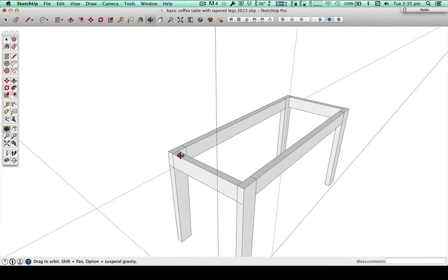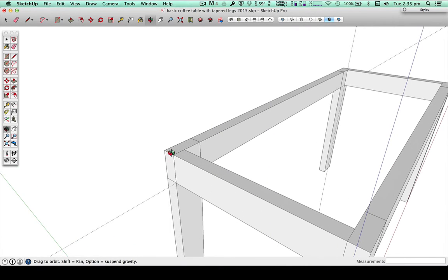So what I'll do is just start drawing the tabletop off to the left. I'll show you a trick while we're there, might as well. I showed you before how you can put a guide on a line. We can just grab a line down there anywhere, stop it here. And I might start drawing my tabletop along this guide. The other thing I can do is just click here and drag from an end point rather than the edge and just create a little point out in space. That's a handy one for your tape measure to do. So that hot point there is the same level as that. So at least I know my tabletop will be level with the top of my skirt and legs.